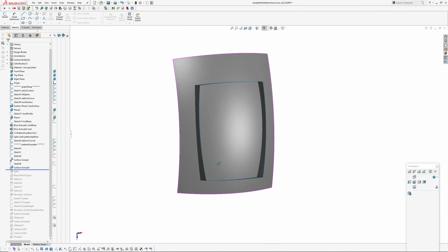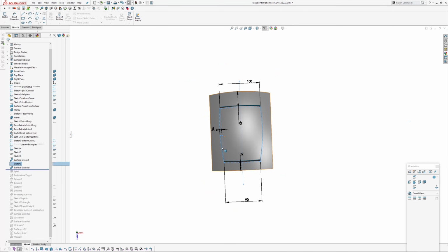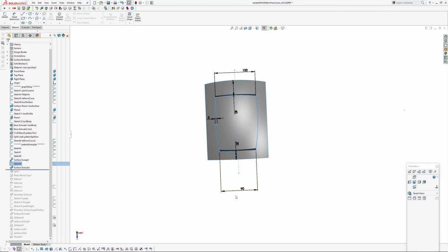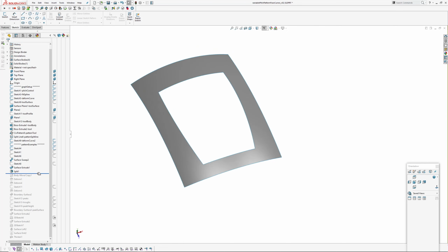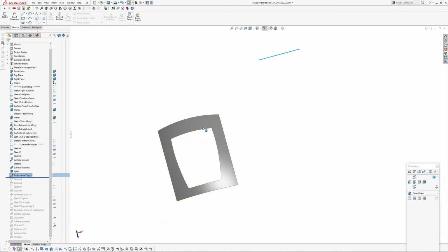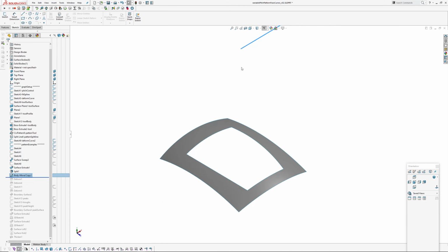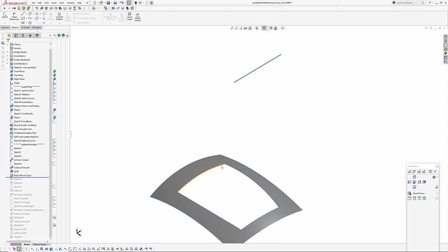Then I've created my split where I want the pattern to exist within, and each end's independent, so you can tweak it. And then I've split that surface and made some copies of the tool surface, because I think I need 3 on this one, because what I need to do is deform my variable pattern tool to this end, and also to a cross curve in the middle.